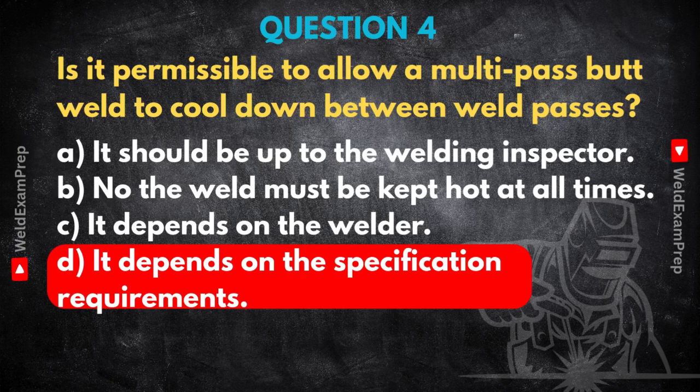Right. But the risks are significant. Cooling too low increases hardness, reduces toughness, ups the cracking risk. Letting it get too hot degrades toughness through grain growth. These aren't always obvious visually, but they create hidden weaknesses that could lead to failure later on. That's why following the WPS and inspection is vital. Underlines the importance of diligence at every single step.